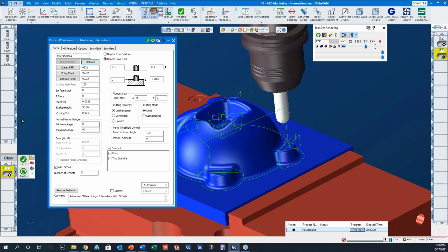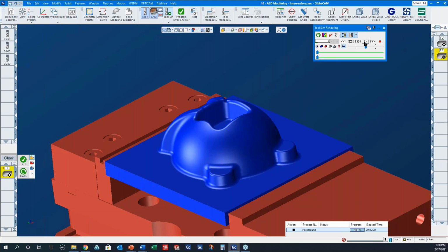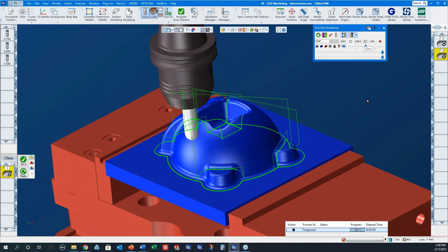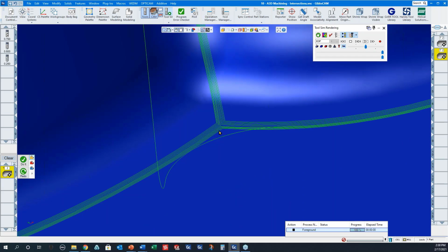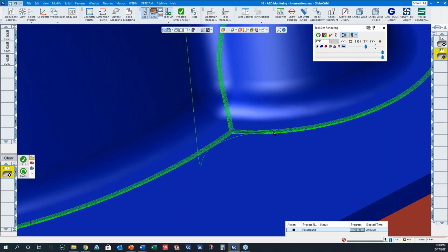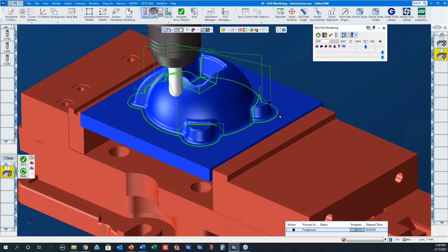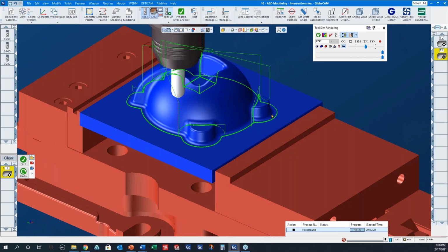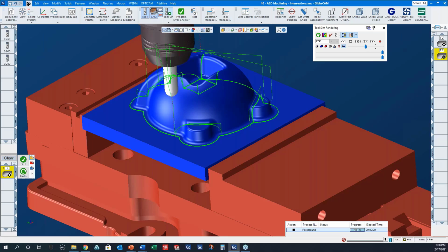But on this next one, I've got with offset, much like what we did with the engraving, the projection machining. I'm going to do 5 offsets, 2.5 thousandths apart. So if you rewind and show what this one does, you'll notice it does 5 offsets out and 5 offsets up from the original. And all those toolpaths are connected together in a very efficient toolpath.